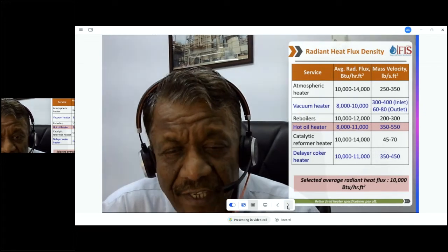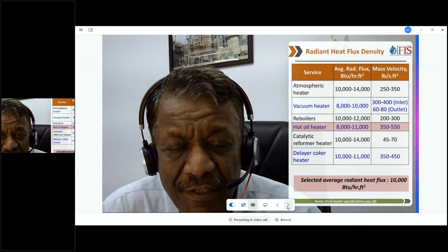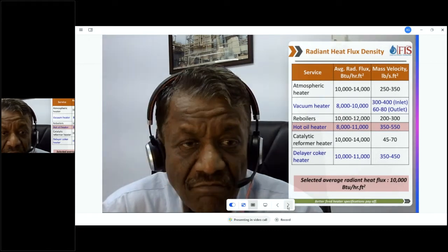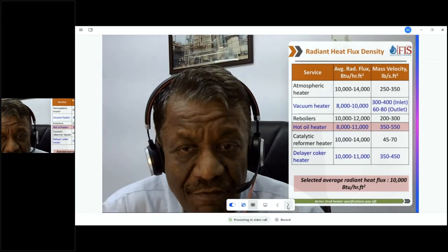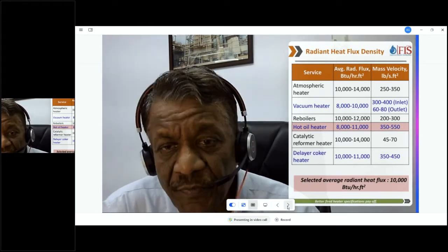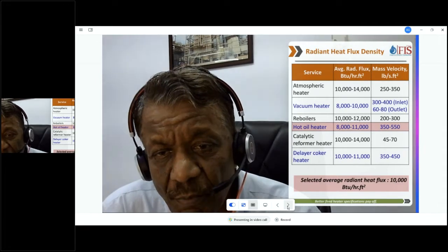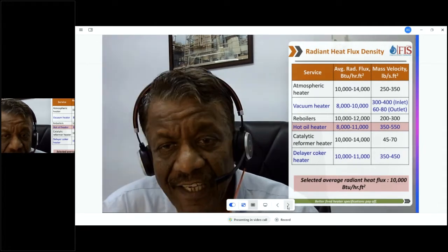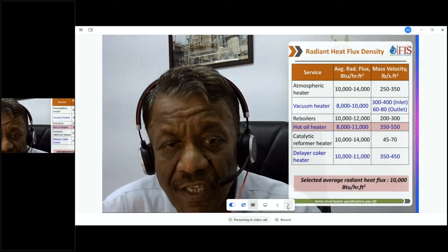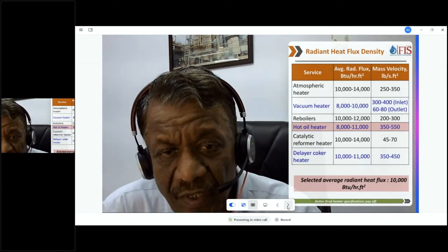And there, sometimes we use fluxes as high as 45,000 BTU per hour foot square. That's how fluxes go up in boilers. So a 100 million BTU boiler may be 1/3 the size of a 100 million BTU heater. So a very, very different approach.